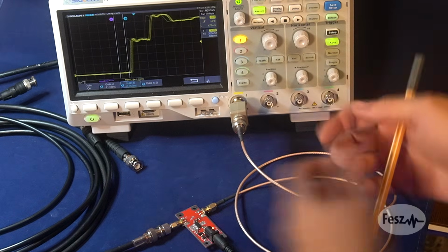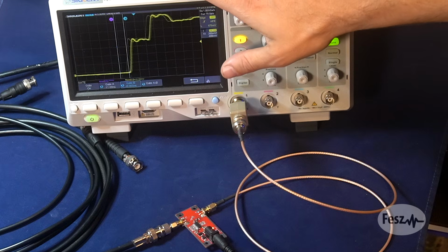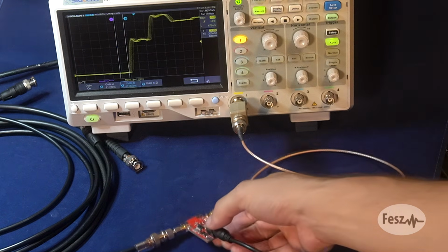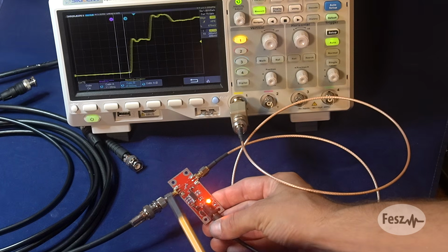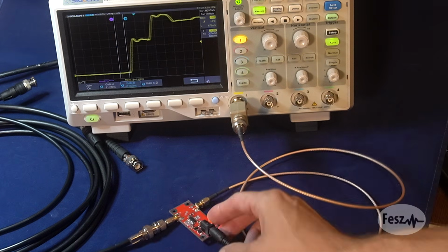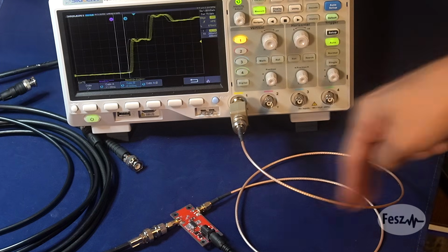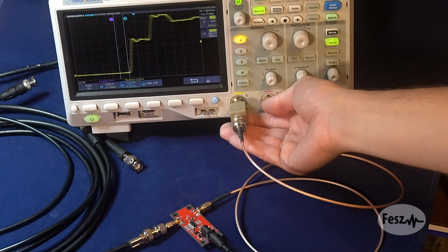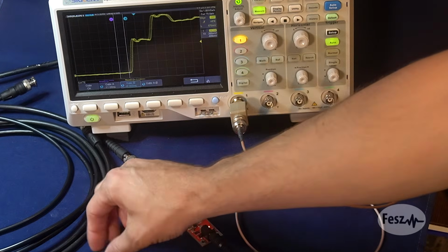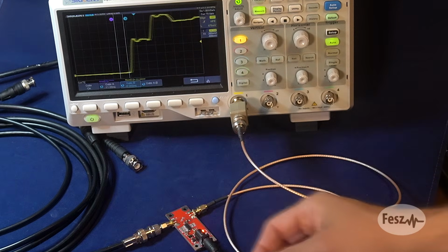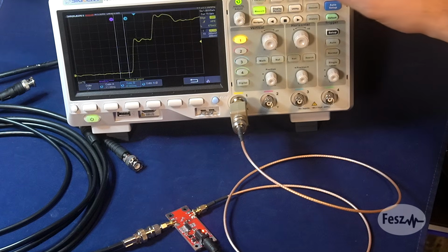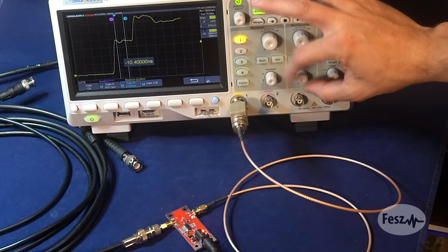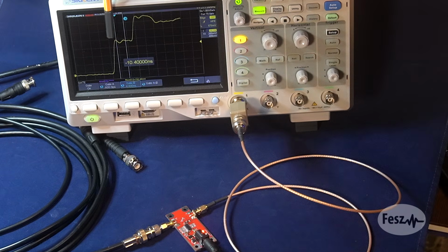To try this method out, I'm using an oscilloscope, obviously, and for the pulse generator bit, this is just a small board with a square wave generator and the resistor signal combiner. On one side, this is connected to the oscilloscope, where I have an inline 50 ohm termination, and at the other end, I placed the test cable. Then the data is read from the screen. So we are looking at the amplitude in the initial flat reflection bit.